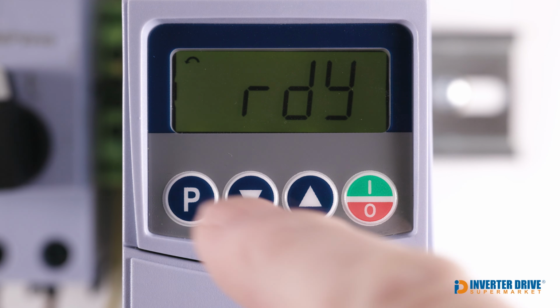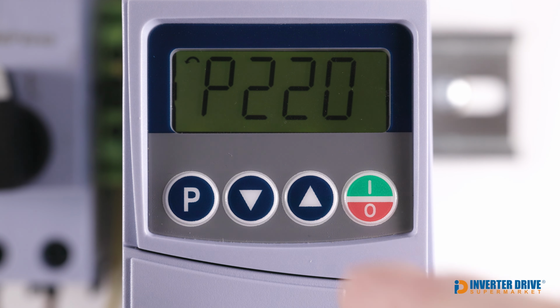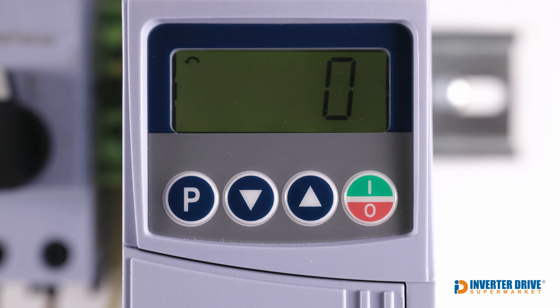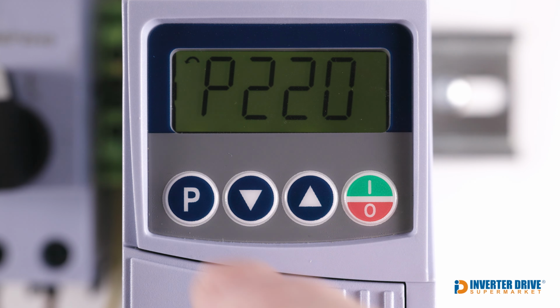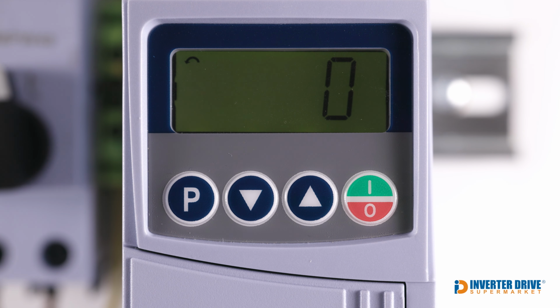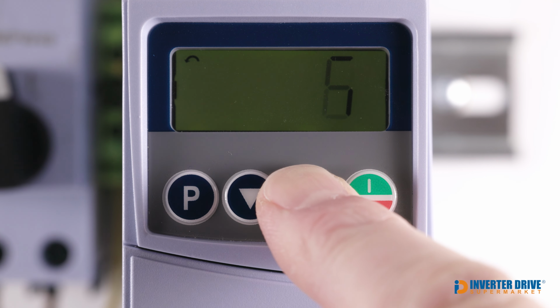The final parameters we'll cover in this video are P220, the local remote selection source, and P224, local run stop selection. By default, both are set to 0 for always local HMI keys, which means the start-stop and up-down buttons on the inverter are used to control the motor. This is the control we needed for this video. However, in part 3 we'll change P220 to always remote so we can connect the digital I/O terminals on the inverter to external buttons and switches. There are several other options for both parameters, but it's not necessary to discuss these at this stage.